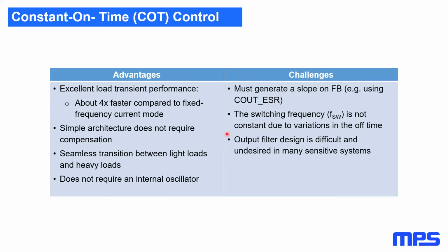I'll go into these advantages more in depth in the following slides, but I also want to mention that changing to constant on time also comes with its own set of challenges that we must address. First of which is that the feedback voltage is what we're using as the input signal to our control, and therefore we require a certain periodicity in the feedback voltage signal. I'll go into more detail on this later on, but it's going to be dependent somehow on the ESR of